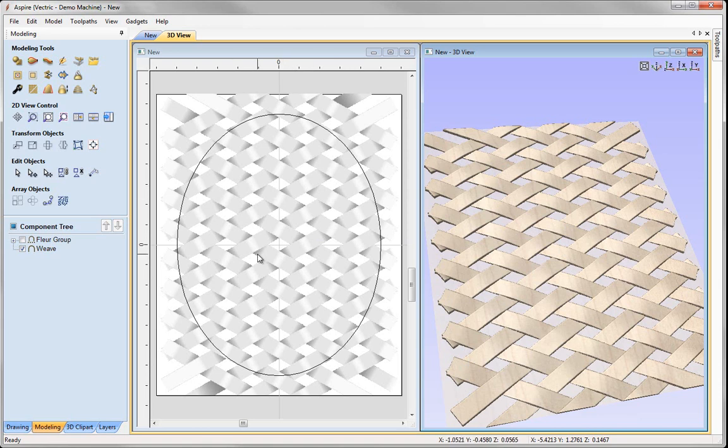I can't do that with the standard fade function in the software because that just fades from one direction to another. But what I can use is a new feature that we've added, which is the ability to use a combine mode of multiply with my components. Much like the add or subtract, the multiply essentially does what its name suggests. The component that you set to that combine mode will multiply all the pixel heights of everything previously in the component list by the pixel heights of that component itself.